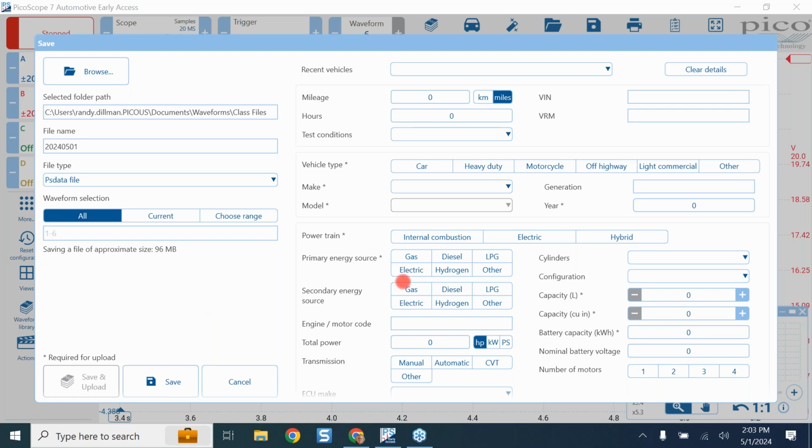Okay, great. And will Pico 7 support an 8-channel Pico? Yes, absolutely. Our 4823 is absolutely supported. It gets pretty crowded. Don't use it on a small tablet. Take your computer and HDMI it over to a much larger screen, because when you get 8 channels running, it gets busy. It gets busy on the screen. It gets busy on the car.